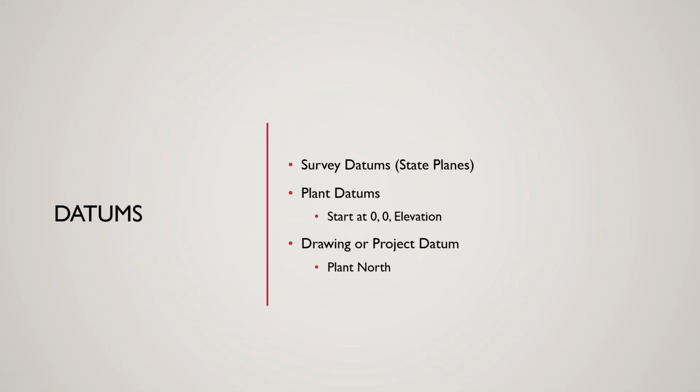This will probably add about $1,000 to the cost of the laser scan, because you have to have someone come out and survey the points you're scanning, and then the point cloud is registered to that. The benefit of that $500 to $1,000 is if you take multiple points around the plant, then your laser scans are registered to that plant coordinate system.